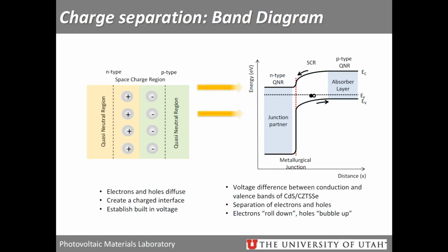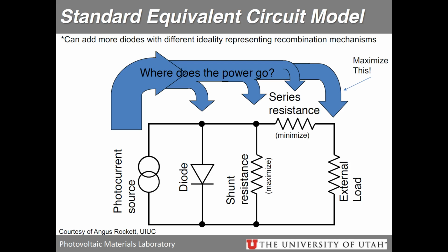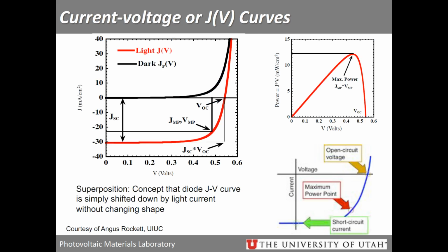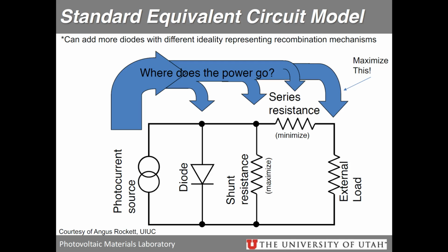Now understand this properly. If you draw the equivalent circuit of this, this is due to the defects in the material. This is due to the back and front contacts. This is the diode, which is due to the p-n junction effect. And this is due to the sun, the photocurrent source.